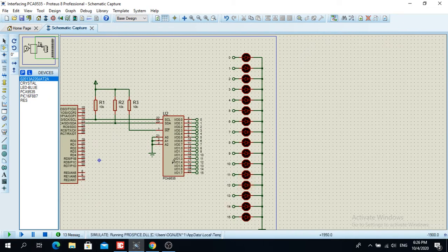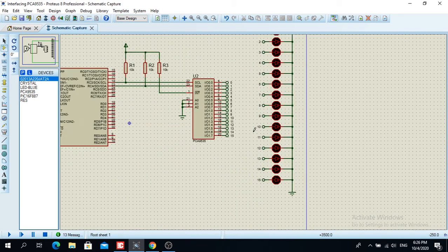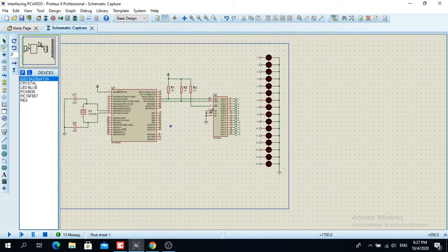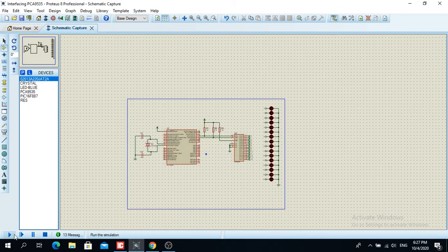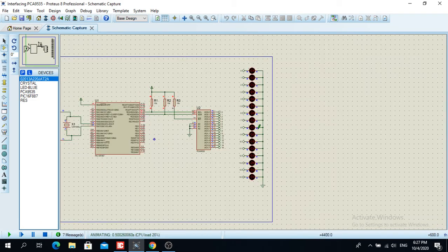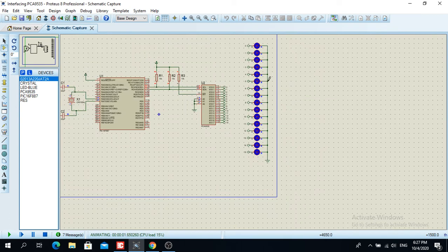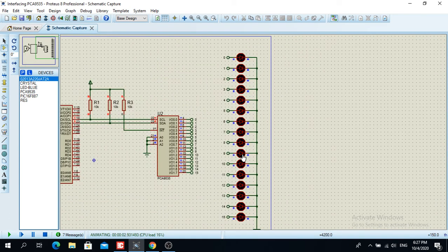And when I start the program here, first all zeros, then 1. As you can see, if I start the program, at 1 millisecond all the LEDs glow, but in real life they shouldn't. It's just the transition when you configure the registers as an output or as an input. But when the program works, it's going to blink: 1 second on, 1 second off.